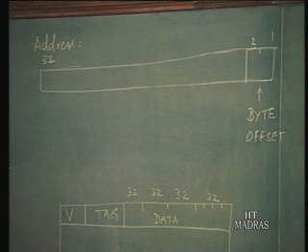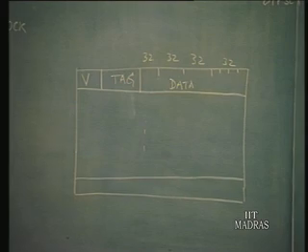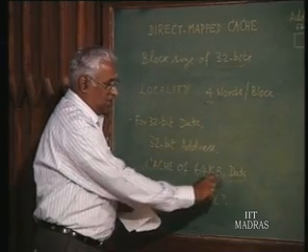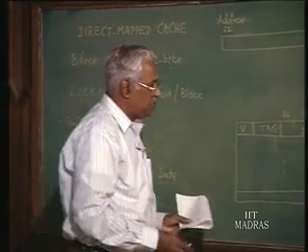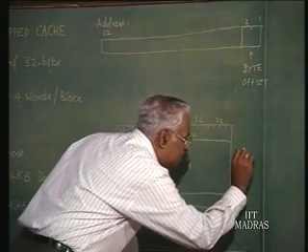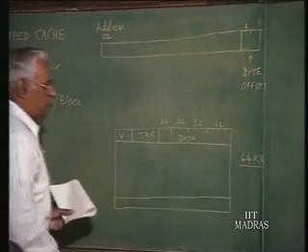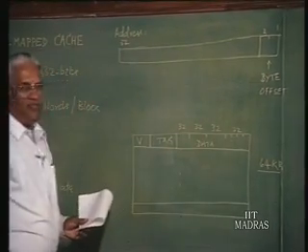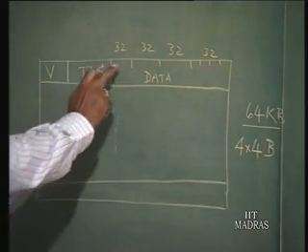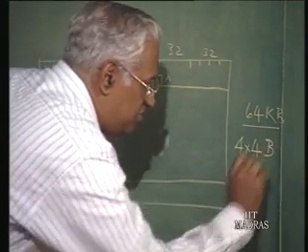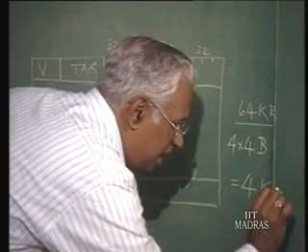Good. Now, the cache will consist of many blocks like this. Now, what is the size? It has been given to us that cache of 64 KB data part, that is the data part alone is 64 KB, which we worked out earlier. From that we can see how many blocks are there. We have 64 KB, that is data part alone, and each block consists now of 4 of 4 bytes, that is 16 bytes. So, we have this divided by that, which will be 4 k blocks.